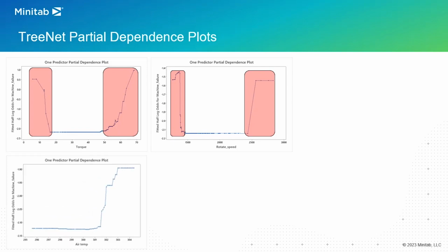Now, as far as the remaining variables, there's this air temperature sensor, and from here it becomes clear that when that air temperature sensor increases above something like 301 Fahrenheit, there is an associated high possibility of machine failure. You can think about it as the sensor that is right there under the casing of the power module of the turbine. So when that turbine is starting to overheat, the air temperature shoots above 300 something degrees, and that's where you have high odds of failure occurring.